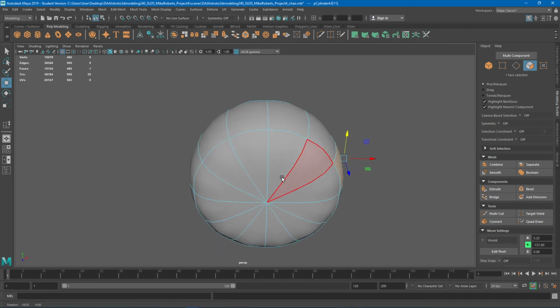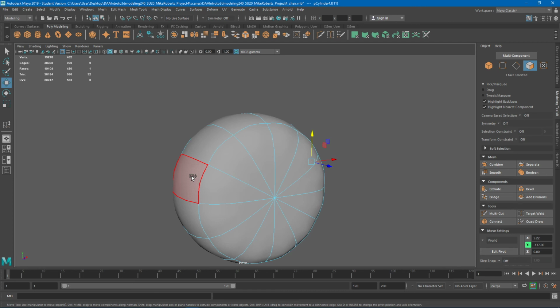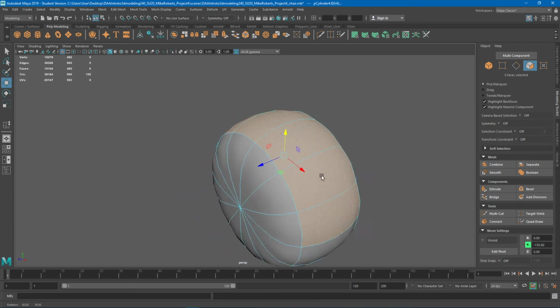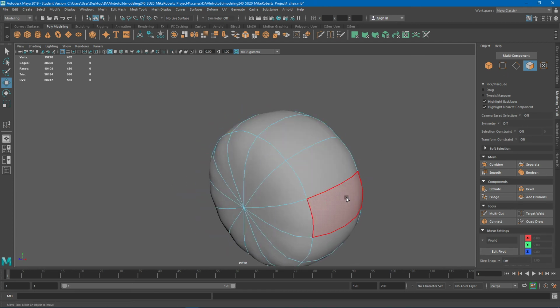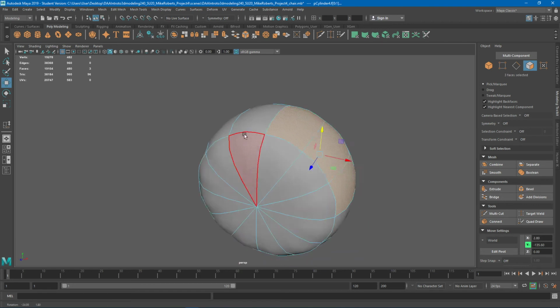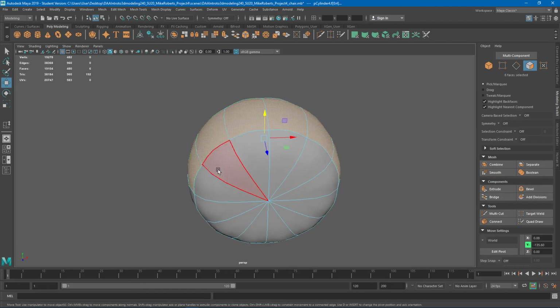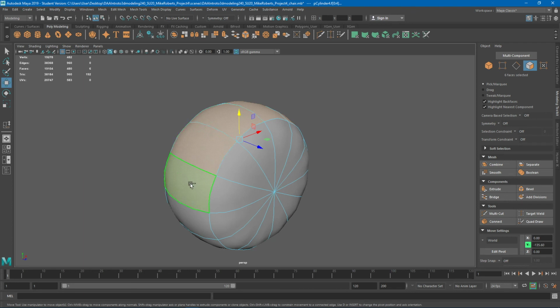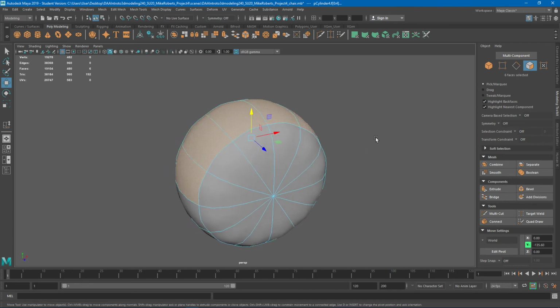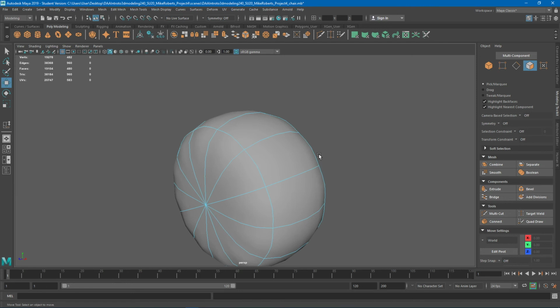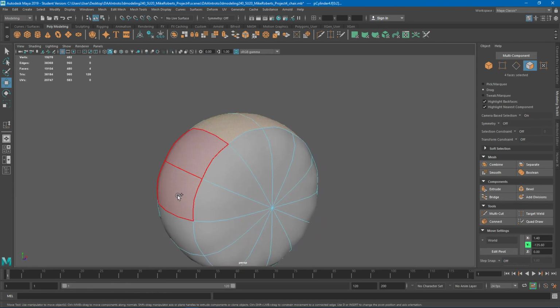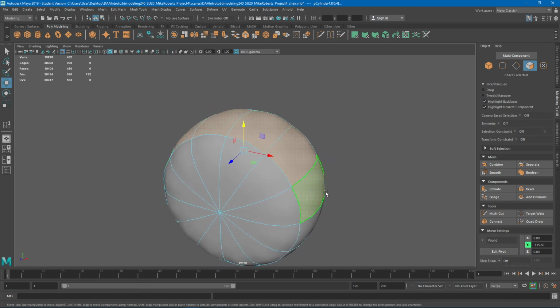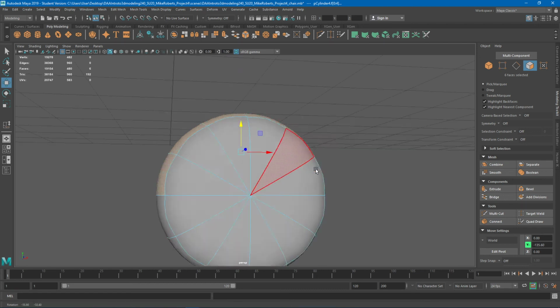Select the face, left click on it, then shift double left click, right? Of course, if you want to, you can do it one at a time: left click, shift left click, shift left click, shift left click, because you have to keep adding one at a time. But you can even use drag, right? The quick key for drag is tab. You hold down tab. And you can always just do this quickly as well. So honestly, things like range selection and drag select are faster in these situations. That's why we have them available. They're great selection options. All right.